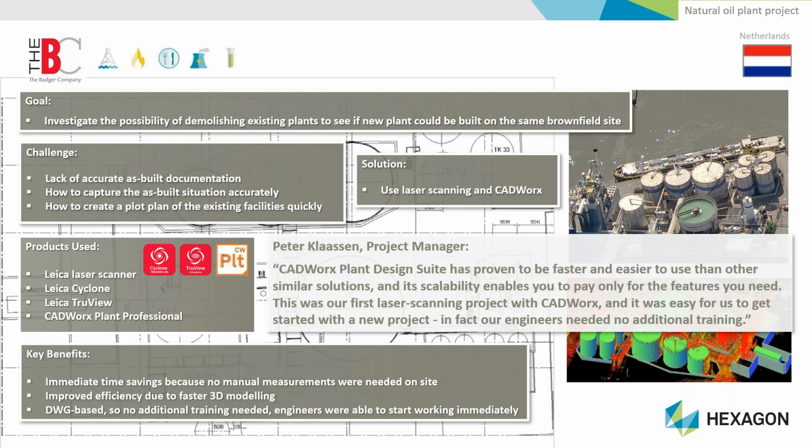Of course, they saw immediate time savings because they weren't doing a manual survey. They were using laser scanning, and of course that fed into the CADWorx solution. Using the modeling here, they were able to obviously create this model very quickly. And the fact that CADWorx, as you know now, is a DWG-based application, that meant, because the designers working on the project already understood AutoCAD, that they were able to start work very, very quickly.